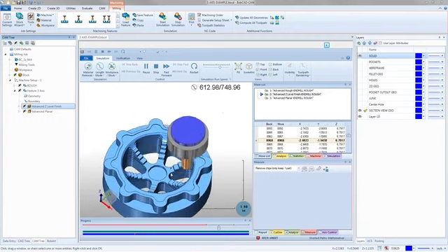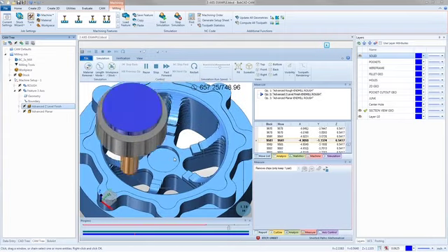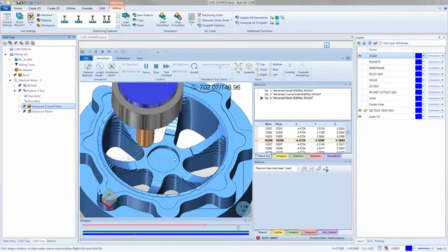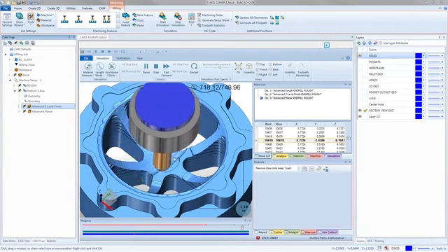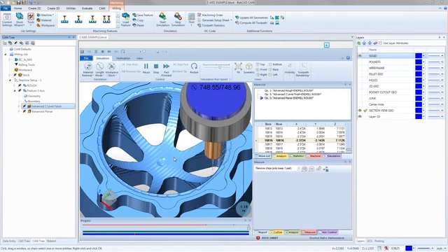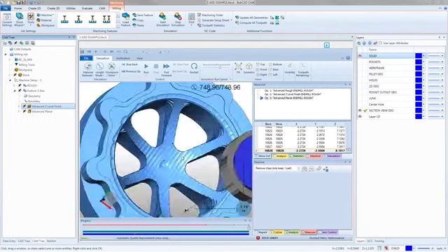So right here we can see it's interrupted cuts anyway, so I don't know if this is the way you'd want to actually machine this. My main focus here was just to show you that you can create a surface so that you can let your tool bypass these pockets. If you block those surfaces, BobCAD can't cut them, so it makes it real easy to get a nice tool pass.